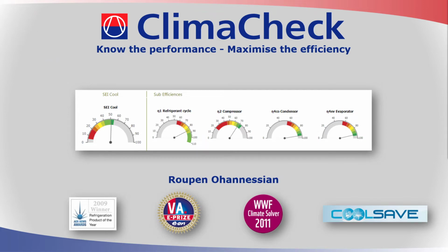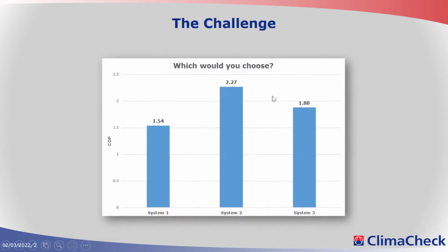COP is traditionally used as the KPI to analyze the performance of chillers and heat pumps. And here's a challenge regarding that. We have three systems with different COPs, and the question is which one we would choose. Now the COP is the capacity that we're getting, either cooling or heating, compared to how much electrical power we put into the system. So the higher COP means we get higher capacity from the system.